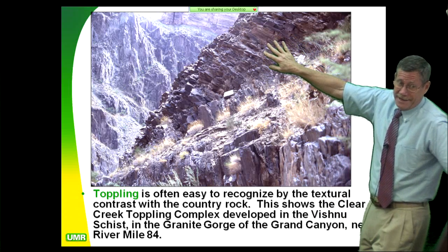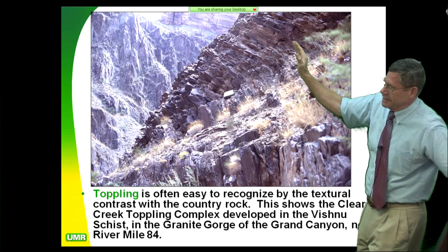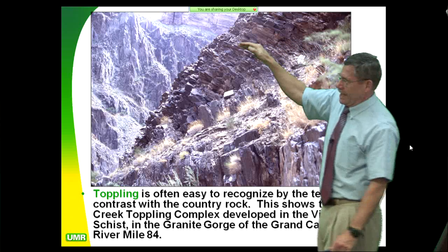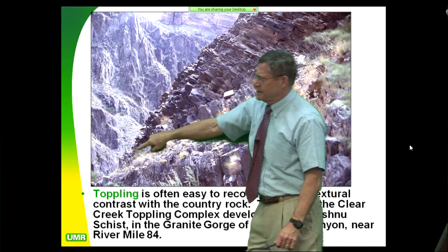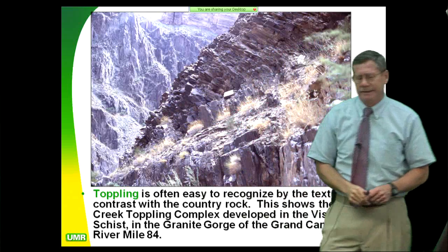That's a rock slide. This thing is failing. You got these big, huge cracks in here. We call that dilation. So this thing is moving over, and the next big earthquake, this thing's going to detach right there, and the whole mass is going to go sliding down the hill.